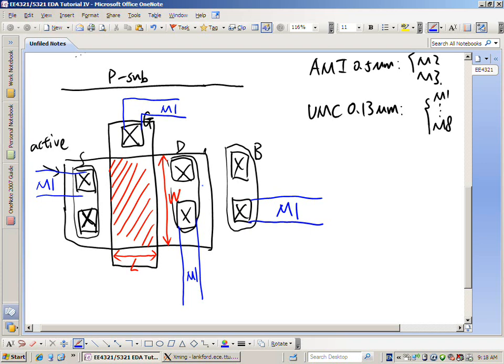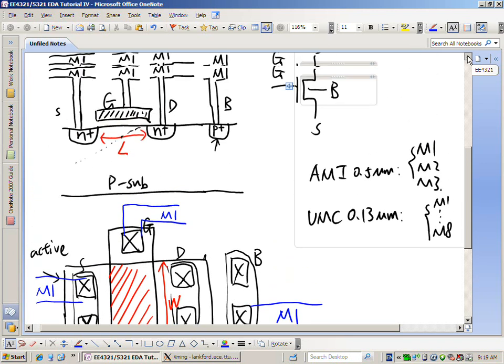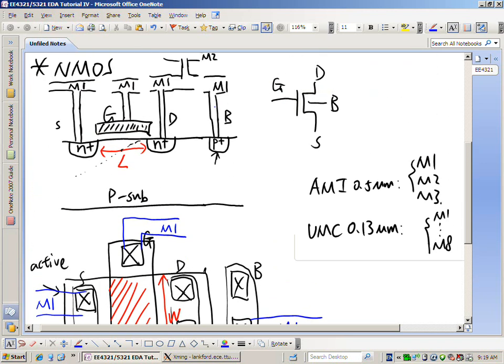The thing is, the more contacts you have, the less resistance you have. Because once you have contact, you will have resistive loss over those signal paths, right? So if you have two contacts, it means you have two resistors in parallel. Effectively, you make the resistance loss smaller.